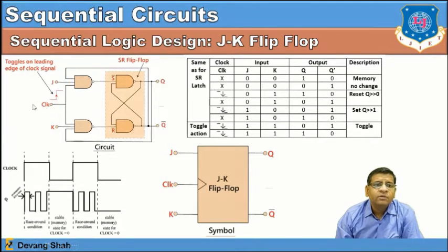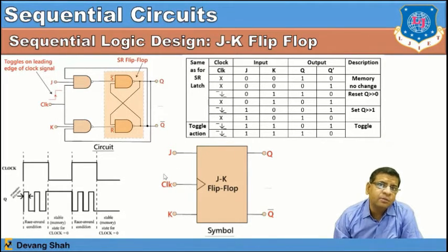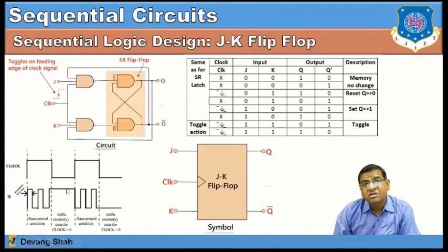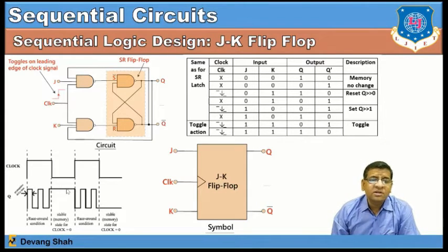That means when the clock comes, the signal is directly taking the previous output, and based on that your output generates a race around condition, continuously blinking like 0 1 0 1, and after some time you have a stable state, right? So this condition is called the race around condition. That means two signals, or you can consider three signals, are not coming at the same time simultaneously. Because of that, it will generate a race around condition, right?